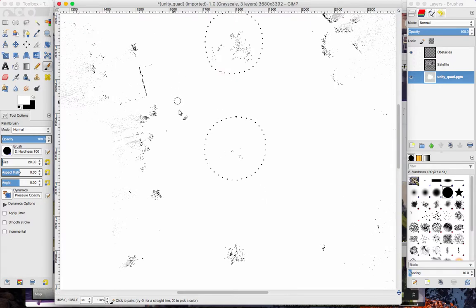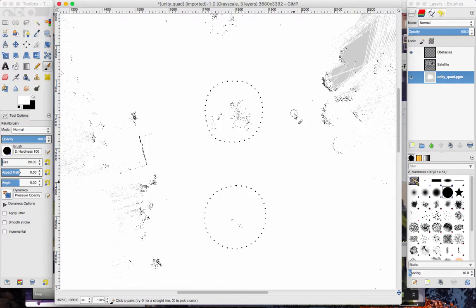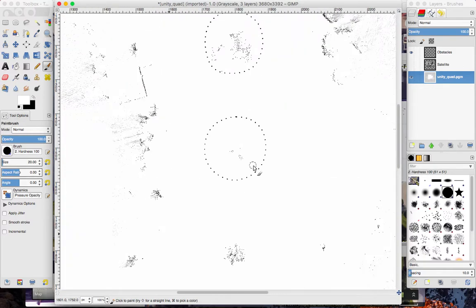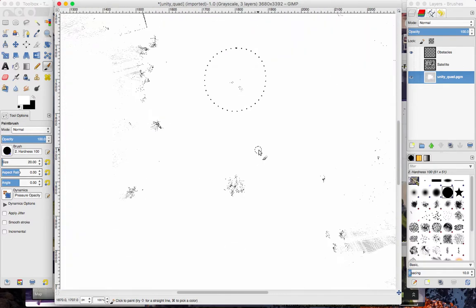But if you had stuff or people that were in the map while you were mapping that you don't want the cart to get confused with in the future, because the person isn't actually there anymore, or a car was parked that you don't want it to care about, you want to erase those so that it's not showing in the map. You can add or remove anything you want, but be careful not to do it too much, because the more you modify this map, the less confident localization will be, to a degree. So you basically are done there.